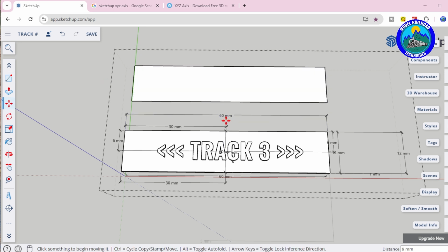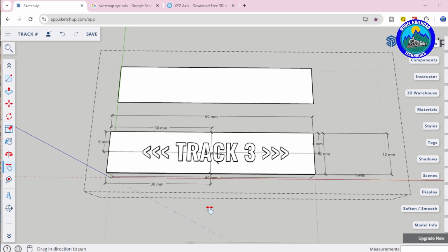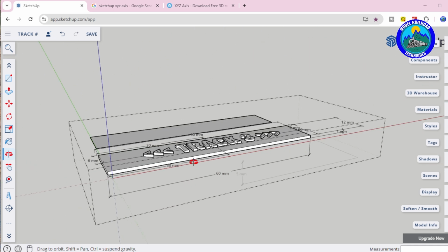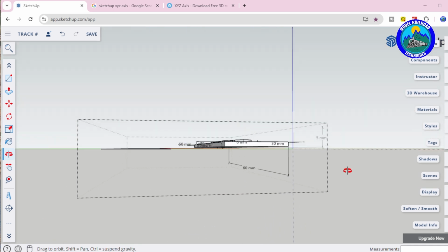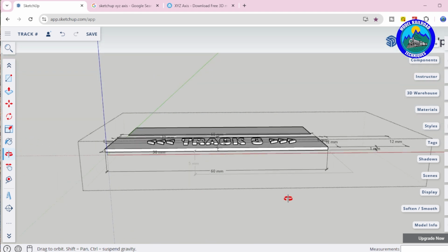From there, we've got other ways to move around the planes or the axes, so to speak. We've got pan, so H we use pan, then I'm holding the left mouse button down and you can go from left to right, hold, and then it locks it. Then we can go to the orbit key, which is really cool, because you can actually start looking at this entity or object in 3D. So it's 0, left mouse button again, and you can have a look around. You can see how my new one on the left here, which is just a black line, does not have a Z axis to it at all.